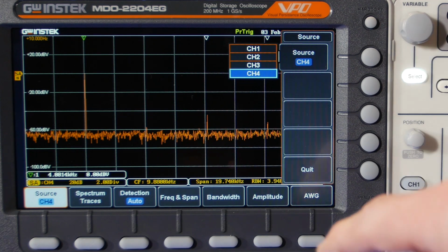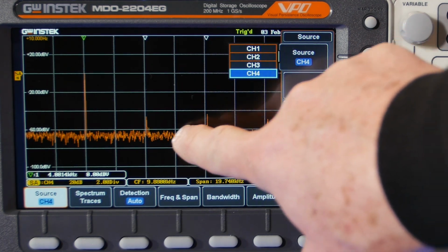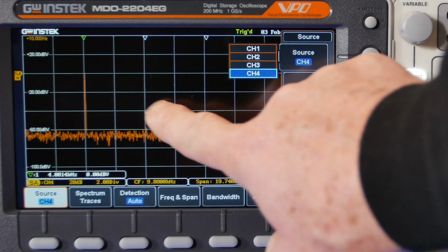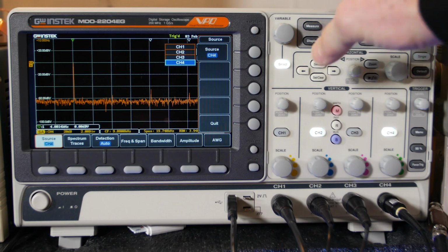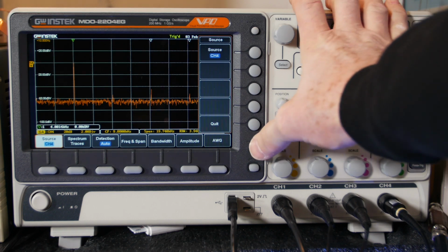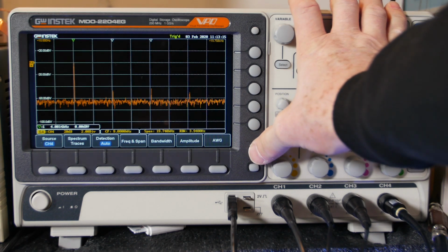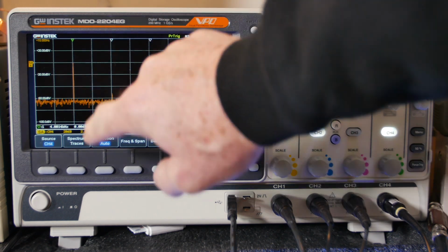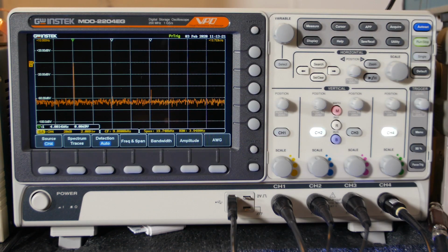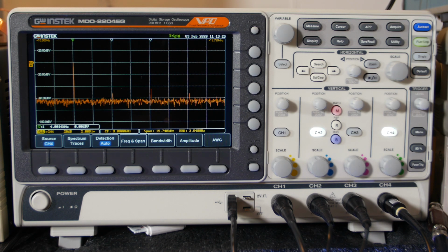Okay, there it is. Wow, look, there is a little bit of a spike here and here. So see, they're coming from the input. So that's good to see. Well, okay, so they are coming from the input. The input is around 0 dB. Remember when we were looking at voltage mode, it was about 1 volt. So they are coming from the input.